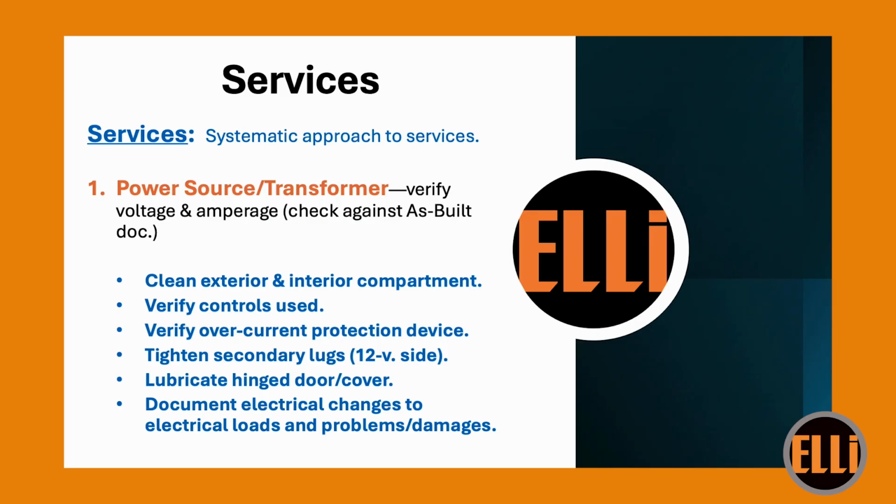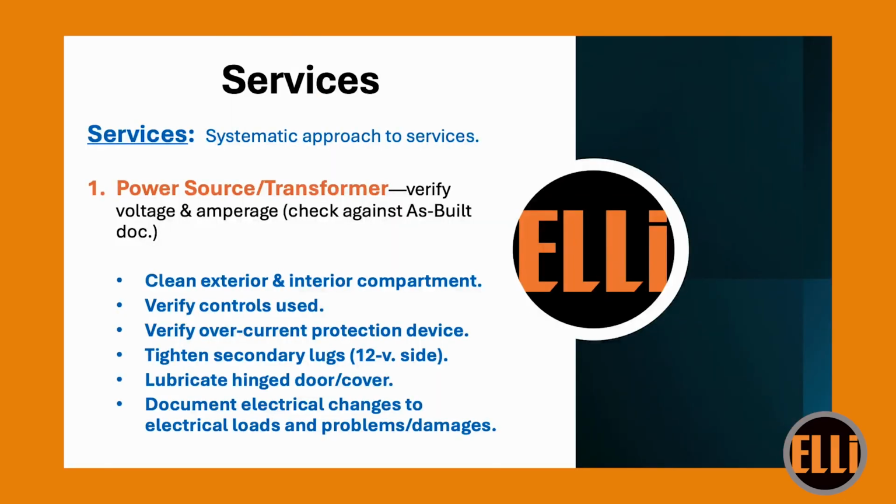So the first item, and I always start off with going to the front of the line, basically, where the power source is. Okay, so power source, transformer location, that's where you start on your services, especially when it comes to troubleshooting. You always want to start there and then work your way out.